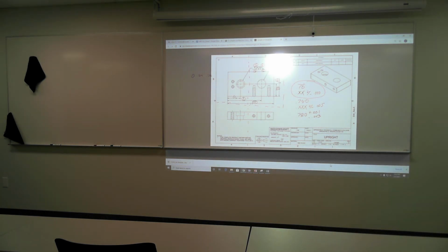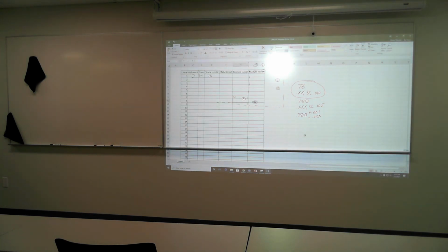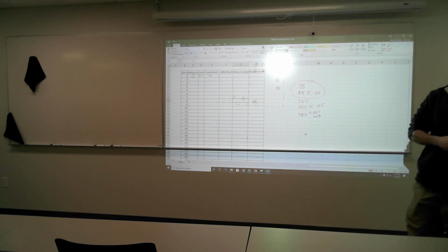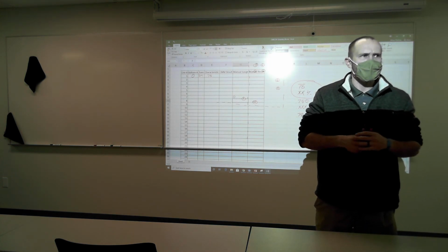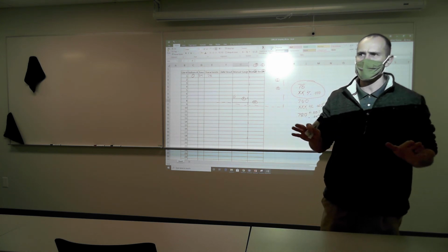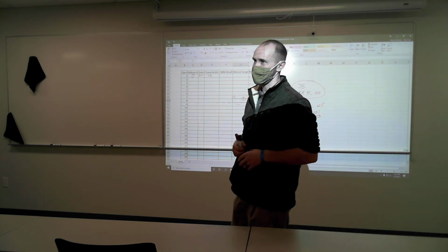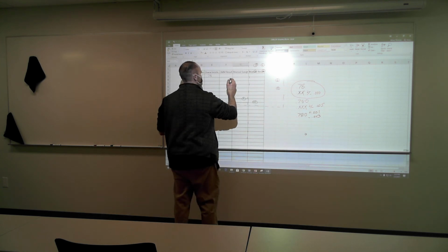Caliper. So what's the rule of thumb for calipers? What's the limit on the sensitivity or precision of calipers? Yeah, the 10th. Calipers, I would say plus or minus 5 thou. I'm very confident that I'm accurate within 10 thousandths total tolerance. In fact, to be fair, I probably trust my reading with calipers to about 3 thousandths total, maybe 5 thousandths total. But if you say calipers are good to plus or minus 5, you're well within that limit, right? So we got plus or minus 10. Yeah, calipers are fine. That's 20 thousandths total tolerance. We'll say calipers.